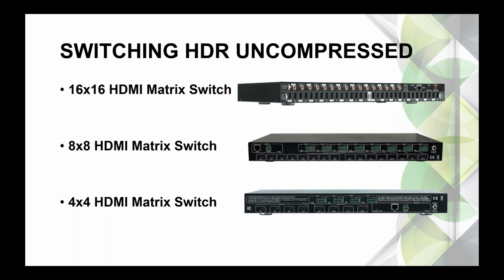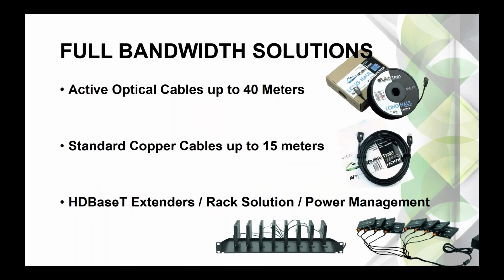They have built-in EDID management on every port, so you can manipulate every port's EDID. They also have built-in test patterns, so you can actually test basic sync source repeater functionality with actual 4K and 2K test patterns. IR, RS-232 controllable, IP controllable, really nice user interface via IP. All the drivers that you're familiar with are available, Control4, RTI, Crestron, and the like.